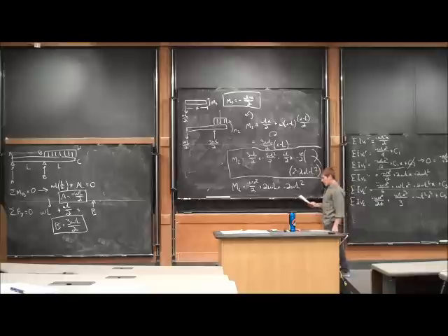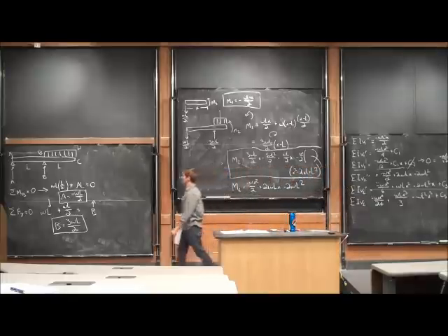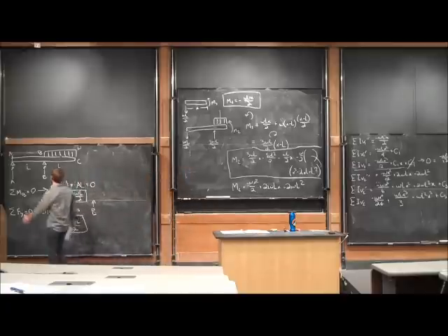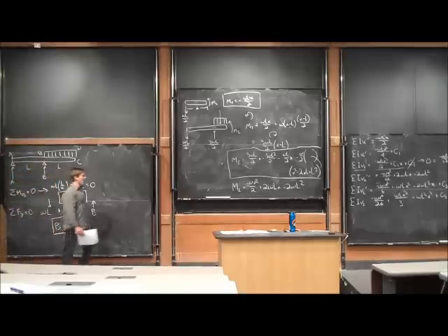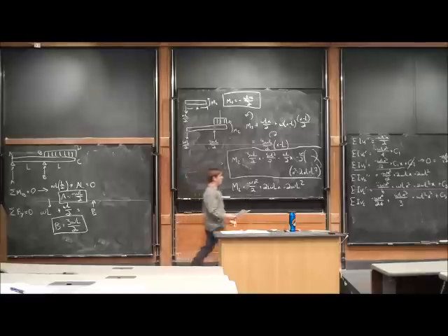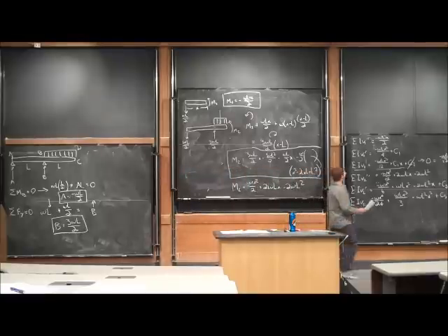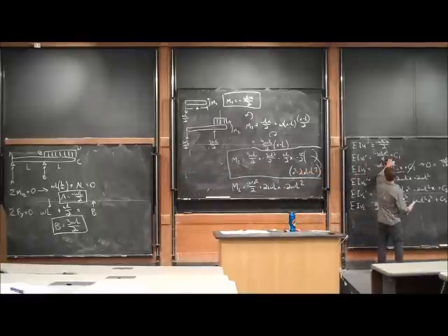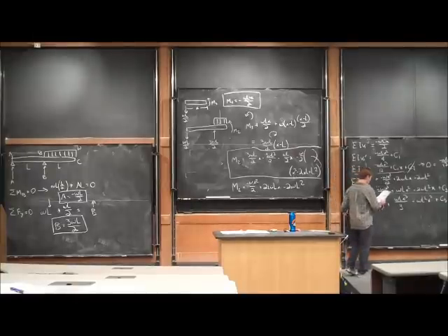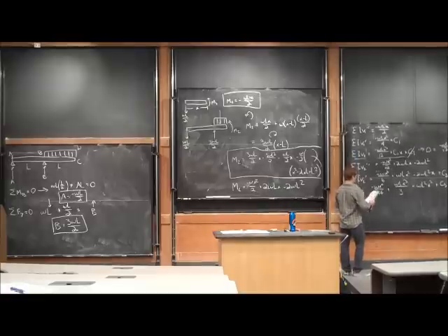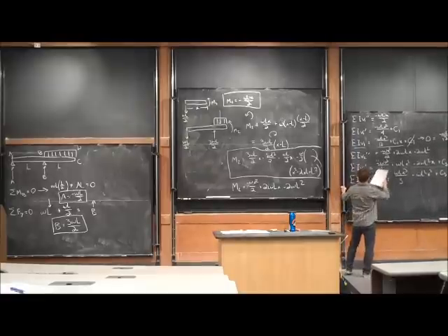So, our next boundary condition we want to apply is because this beam is continuous, we know that the slope at this support is going to be the same for both sides of the equation. So I know that V prime of 1 at x is equal to L is going to be equal to V prime of 2 at x is equal to L. So I can apply that boundary condition, and we know what C1 is now.